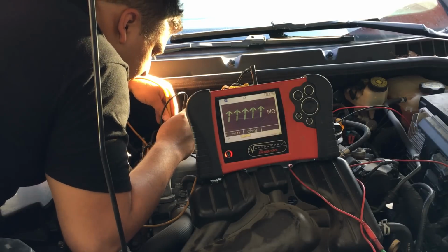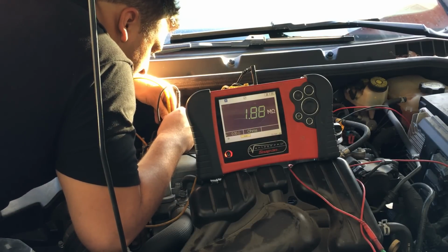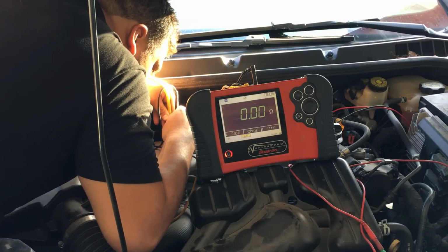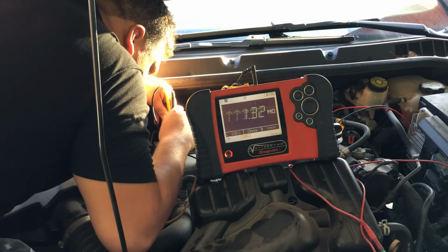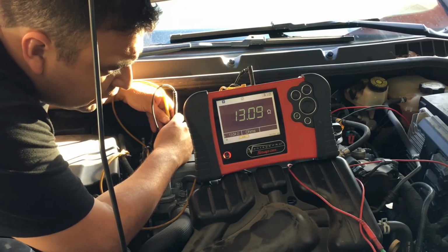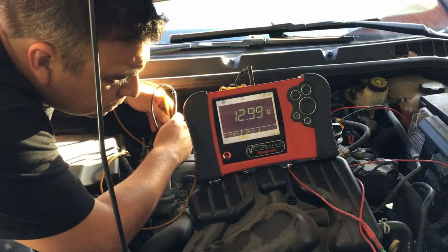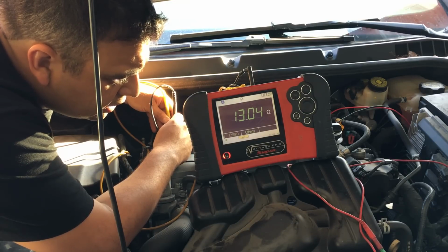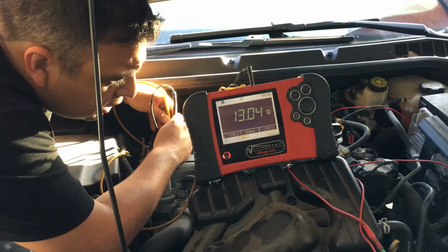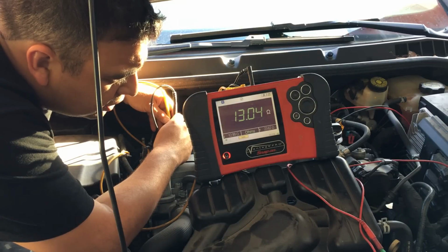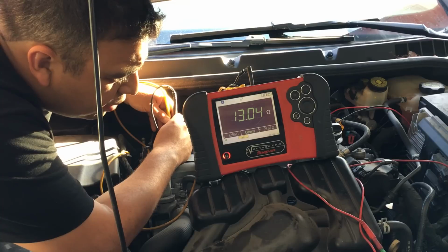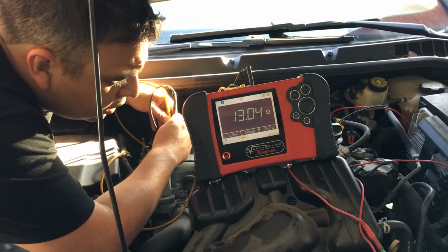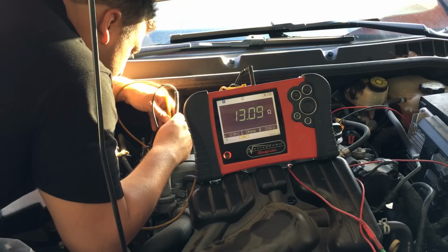I'm going to go ahead and touch my leads. We're now going to be looking at the exhaust solenoid. Let me get a good connection here, right there. Take a look at the reading. Looks like we're reading about 13 ohms of resistance. And immediately what I notice about this reading is that it's staying pretty steady. It's not jumping around like the other one was. Yeah, so around 13 ohms of resistance.